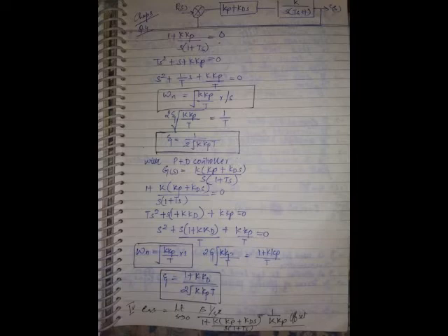Output of an inverter is plus Vout. It is R2 by R1 into Ve plus R2 by R1 into R1C s Ve, where s Ve is nothing but dVe by dt. So you observe Kp value is R2 by R1, Td value is R1C. What was the time constant of the phase lead compensator? R1C. So we say that this controller is similar to a phase lead compensator.